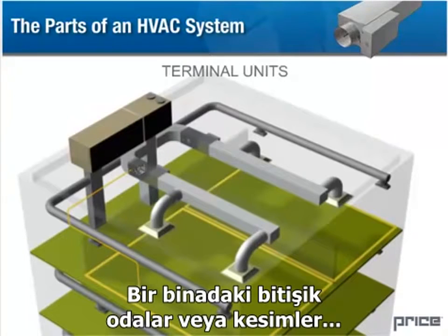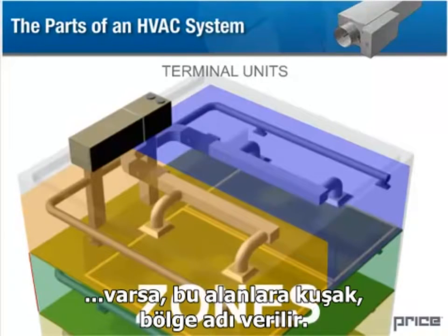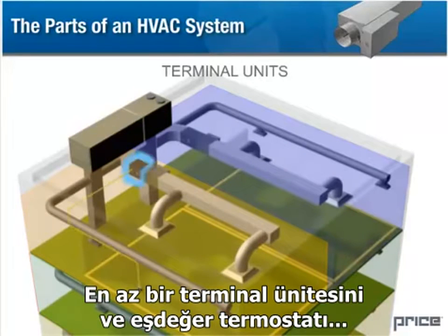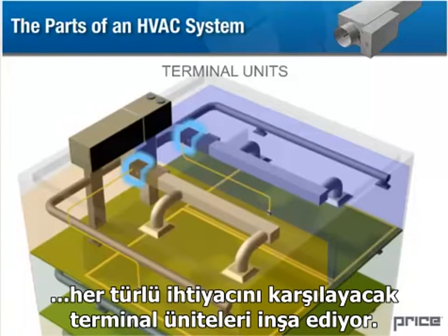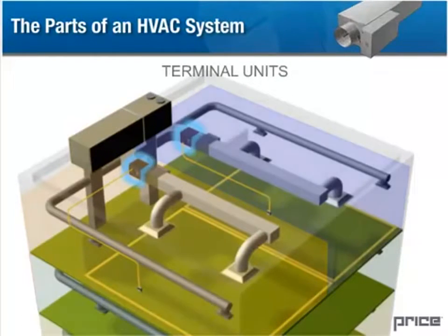A set of adjacent rooms or regions in a building which have identical heating and air conditioning needs are called a zone. It is typical to assign at least one terminal unit and corresponding thermostat to each zone. Price manufactures many different varieties of terminal units to suit all types of building needs. We discuss terminal units in greater detail in the forthcoming terminal units section.